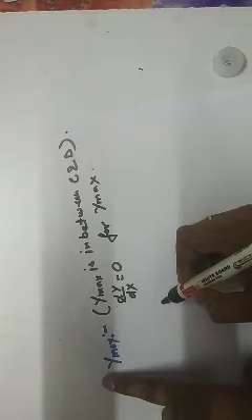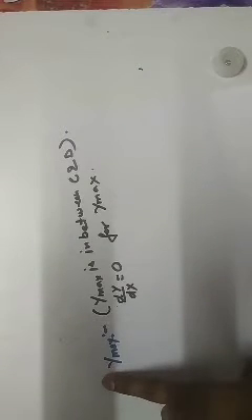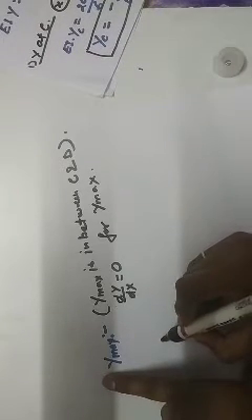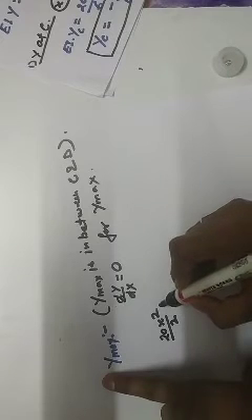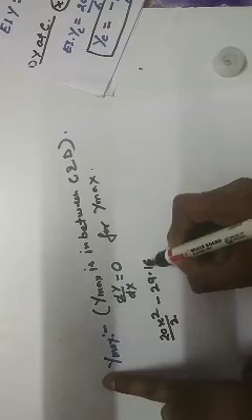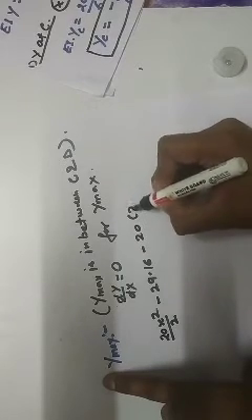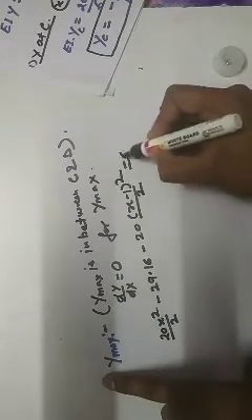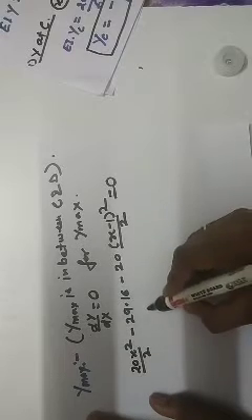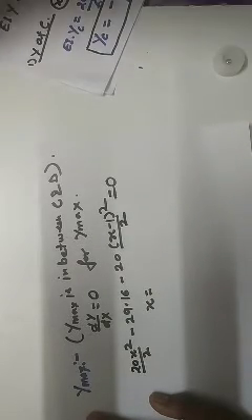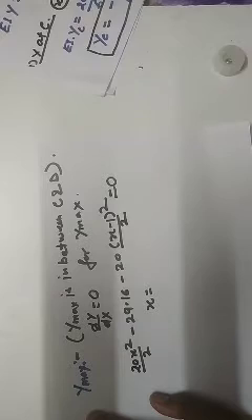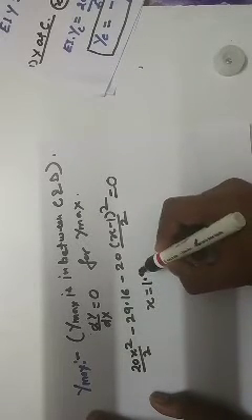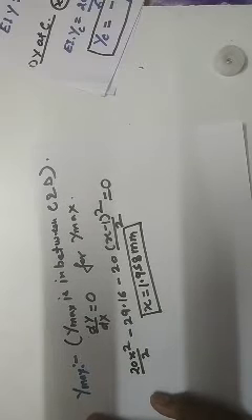Now put in the equation. Put the slope equation equal to 0, and the equation that we have established is 20 x square by 2 minus 29.16 minus 20 (x minus 1) square by 2 equal to 0, right? When we solve this equation, the value of x will come out as 1.958 m. Right? This is the value of x.